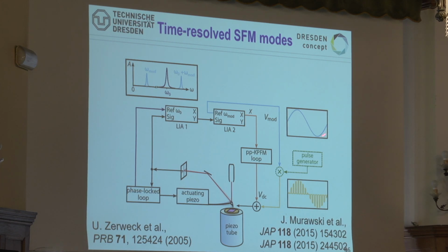Let's take that sine as an envelope and then actually put a pulse generator into it. So you see again, the envelope is exactly the sine envelope, but we're going to really shoot with a pulse generator in very high frequencies. In fact, it's going up to a couple of 100 megahertz in there. So basically what you're doing is an amplitude modulation of this signal here. The envelope is still there. It can still regulate. But what you're interested in is exactly these pulses. Why? Have a look here.